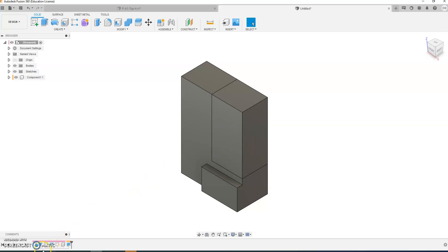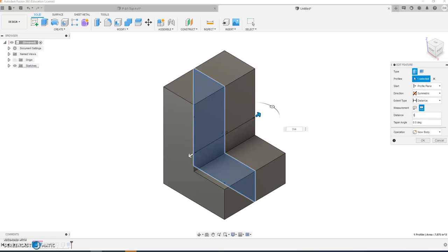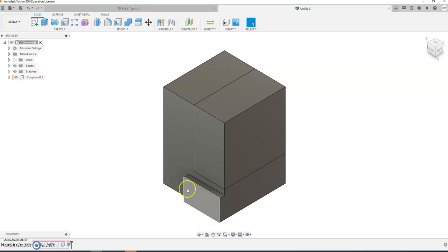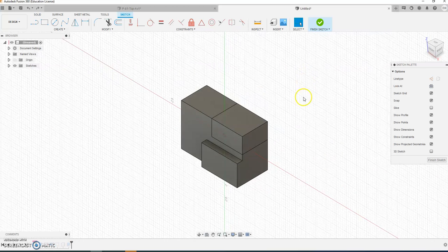Okay, let's say, man, there's another design change. This block wasn't extruded 2 inches. This block was extruded, or sorry, 1.25 inches. This block was extruded 3 inches. So there it is, extruded 3 inches, okay. Since I referenced that and connected to the corners, notice how it automatically changes this other part. I'm going to go ahead and undo my back. You did not need to do those other changes.